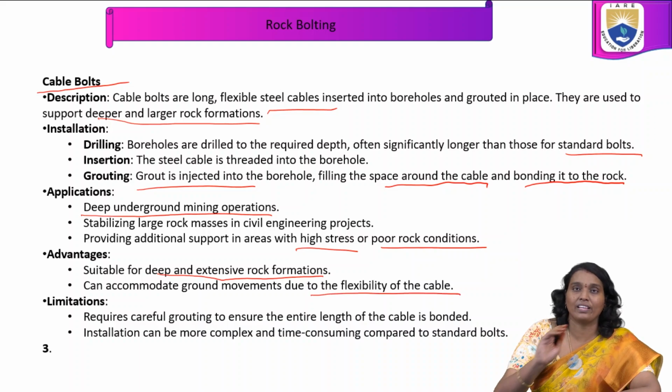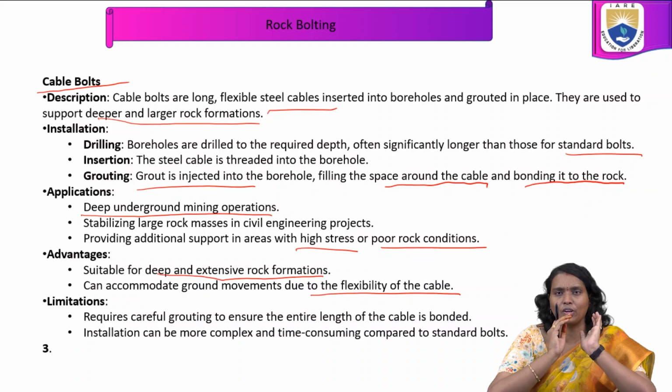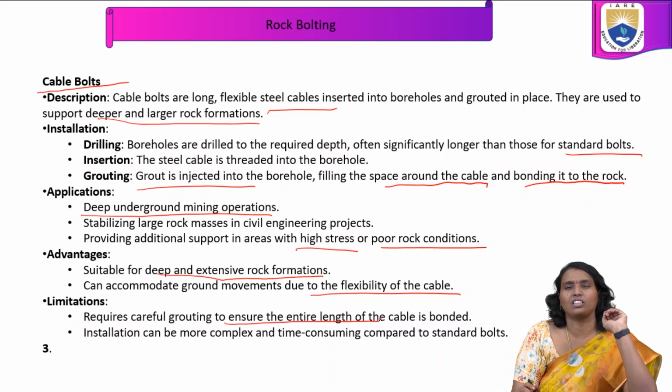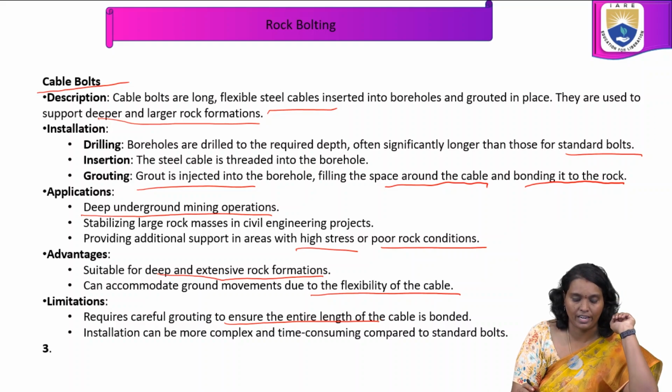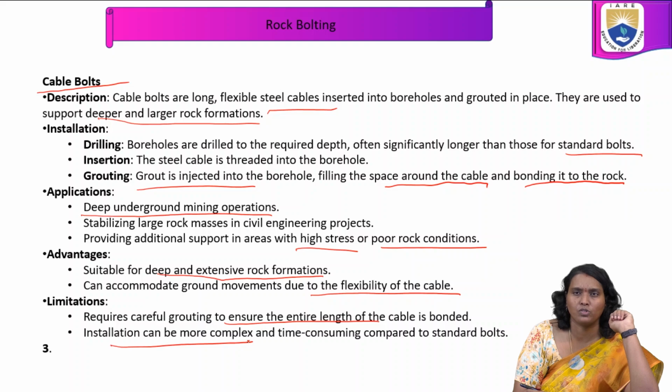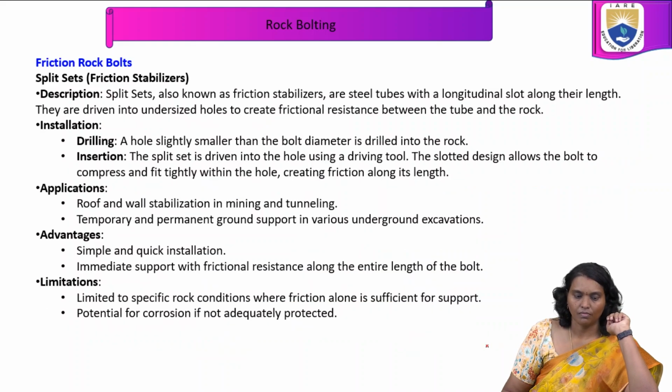There are also some limitations. It requires careful grouting to ensure the entire length of the cable is bonded. Installation can be more complex and time consuming compared to standard bolts.